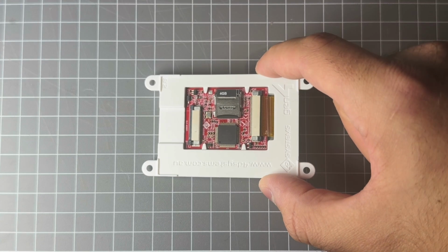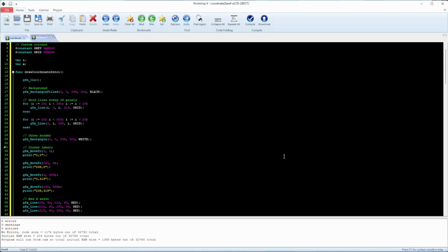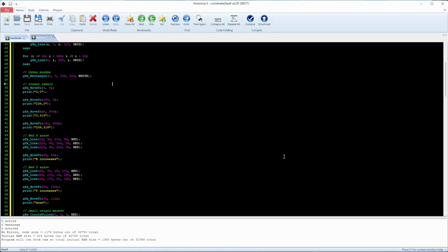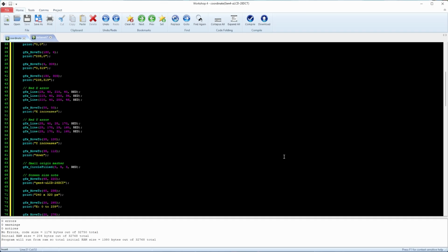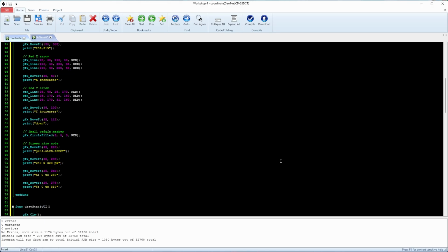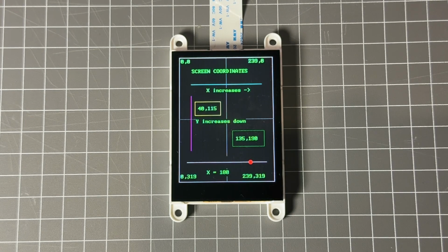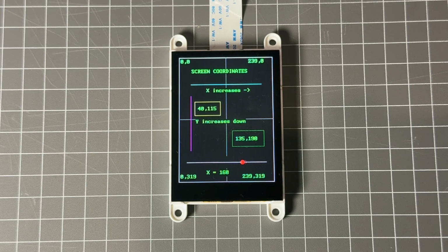For this example, I'm using the Gen 4 ULCD 28DCT, and I'm working in the Designer environment. So this is all code only. No widgets, images, or visual layout tools like the ViSi or ViSi-Genie environments. We're just drawing directly to the screen using 4DGL. When you're in Designer, every piece of text, every line, rectangle, and shape has to be placed using an X and Y position.